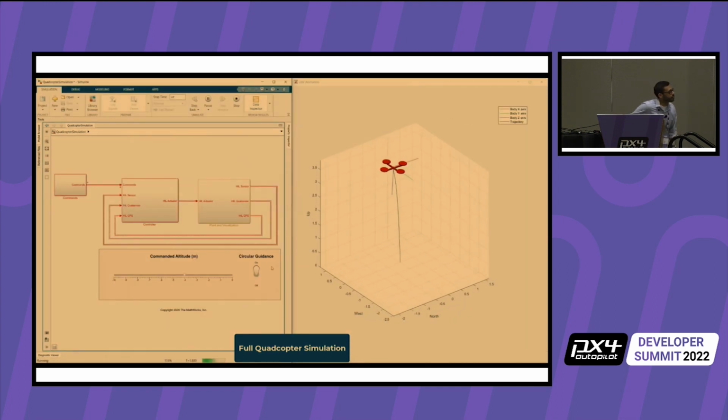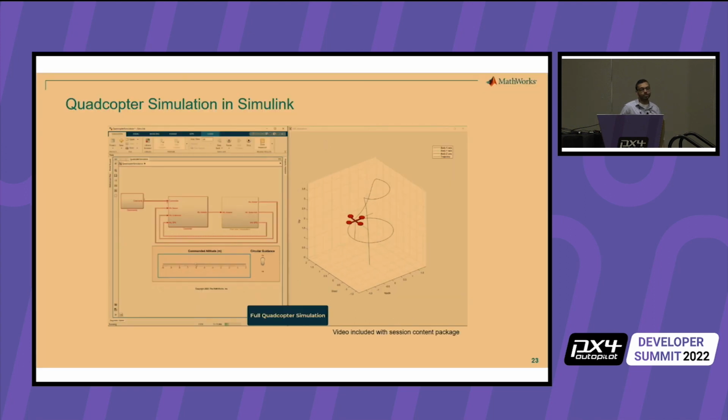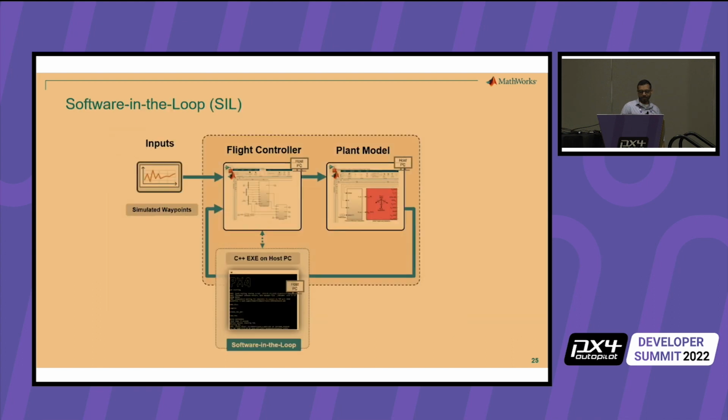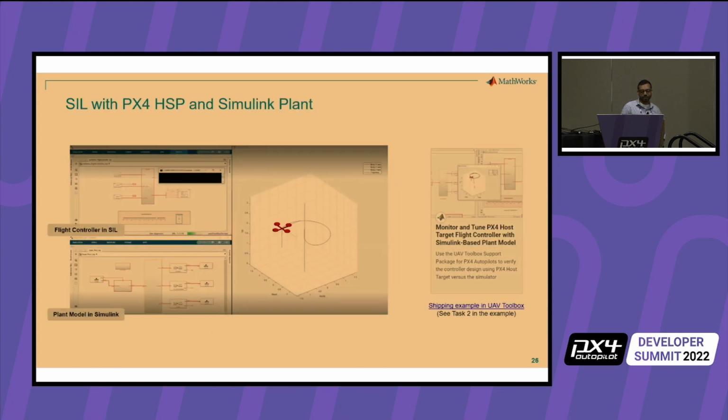And just showing you what we looked at again. When I go and push these commands, those are the commands that are getting sent into my actual flight controller. And the response you can see as an animation. Great. So once we've tested this, we like the response that we get from our simulated drone, what we want to do is go ahead and generate some C code and see what our performance looks like at this stage.